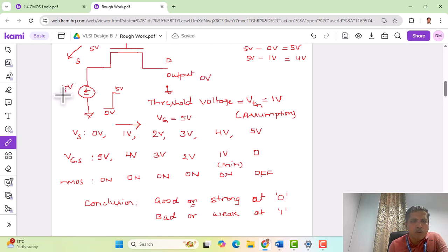On 4 volts and above of source, the transistor turns off. We have seen this condition: the moment it is 4, VGS has already reached the threshold voltage. So with a slight increase in the source voltage above 4, the NMOS transistor turns off. An example is an intermediate value, say 4.1. For that voltage, NMOS will be turned off.